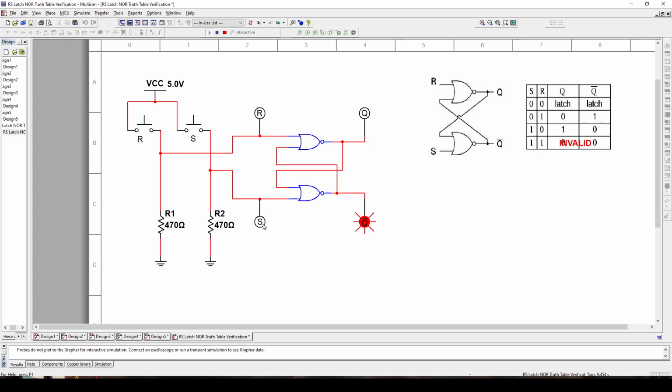All right, and these indicators simulate a set and reset here. So I just put additional probes here. So here's set, reset, set. No matter how many times I press, or reset, if I trigger one condition, the whole device is going to latch into that condition. It's going to stay that way. If I trigger the other condition, the whole device is going to latch or stay in the other condition. So that's pretty much the idea of an SR latch or RS latch.